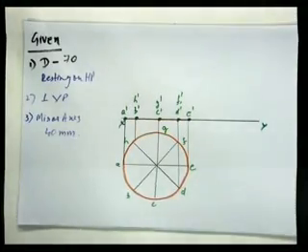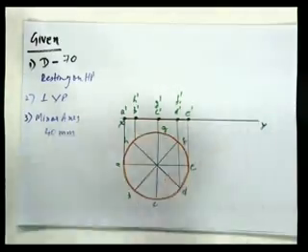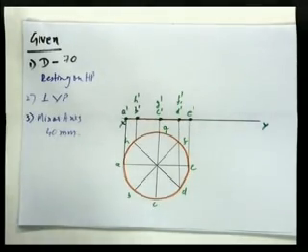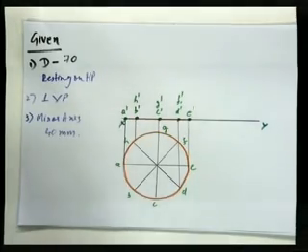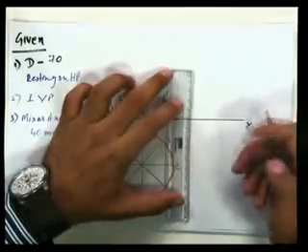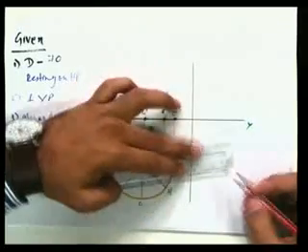Now what is given to us is that this is tilted in such a way that the minor axis that comes is of 40 mm length. So what we need to do is draw two lines which have a distance of 40 mm in this way. Say I've drawn one straight line and I'll take two endpoints.